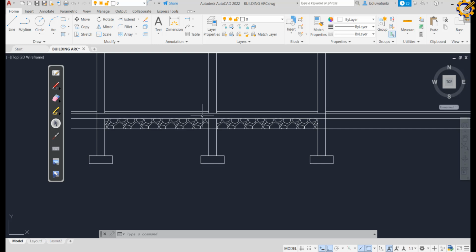Now, in a standard building construction, those of you who are going to go for IT, after this hardcore, before they pour the concrete, you will see something like a polythene sheet. Some people will introduce a polythene sheet or black nylon. It can be either black or white. They will lay it after the hardcore before they pour the concrete. So what is the function of this polythene sheet? That polythene sheet is called a DPC, damp proof course. D-A-M-P, damp proof, P-R-O-O-F, then course, C-O-U-R-S-E, and its function is to prevent groundwater from rising into the building.